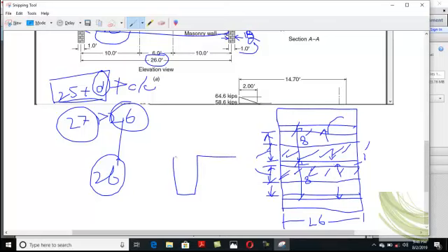And there is a slab on the top of this T beam, so we will consider this whole web. We will consider this 24-inch width. So this portion of slab which you are seeing right here will be counted when we are calculating the width of the beam.